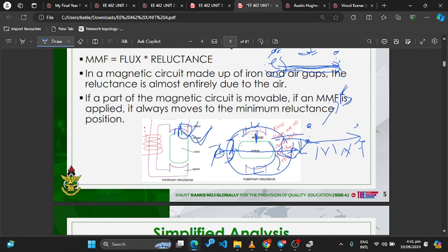So now this is activated, and this one will also want to have least reluctance. So it will cause the motor to align in this way. Then this one will also go off, and maybe there are some poles over here that come on. They also want to enjoy least reluctance, so when they are energized, they also move in that direction.